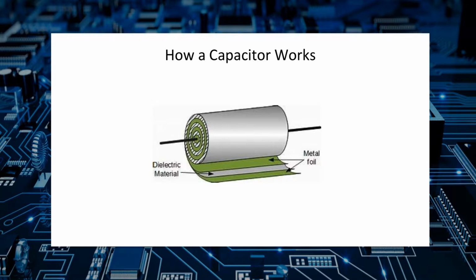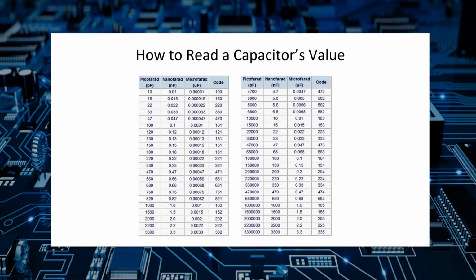In addition to the rated voltage, capacitors also have a tolerance. Usually it's between 5 and 20%, 20% being the most common. Like resistors, capacitors are marked in a variety of ways, including color bands or dots, numeric and alpha codes, or the value written right on the capacitor. The code system used varies by type of capacitor.